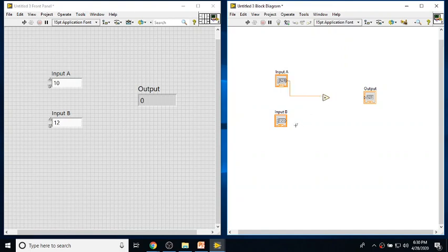I repeat it. I go to this terminal, I touch this terminal. You can see it changes into a wire bundle. It's called a hotspot. That's a wiring tool in LabVIEW. So LabVIEW automatically changes its connector cursor, right? So I'll just come touch this. You can see there is a wire bundle visible. Click, drag, touch here. Same from here to here, right?